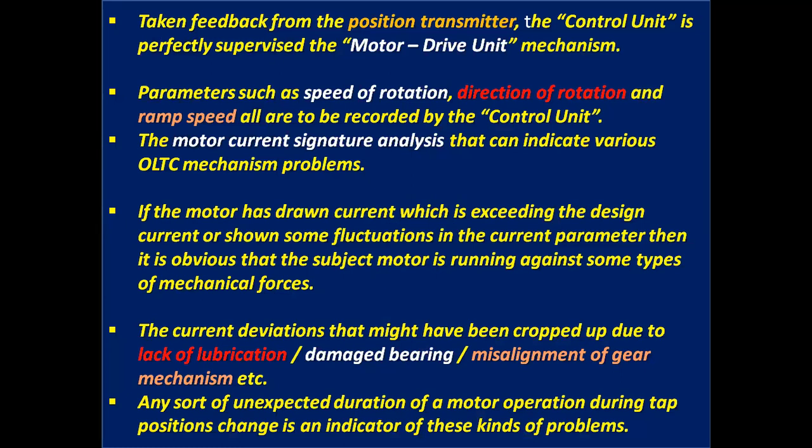Taking feedback from the position transmitter, the control unit perfectly supervises the motor drive unit mechanism. Parameters such as speed of rotation, direction of rotation, and ramp speed are all recorded by the control unit. The motor current signature analysis can indicate various OLTC mechanism problems,